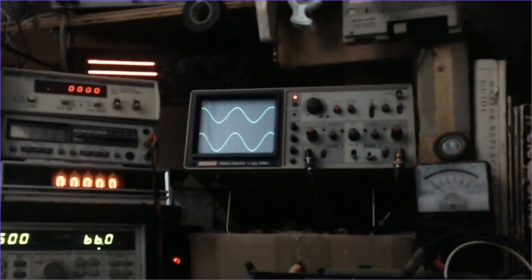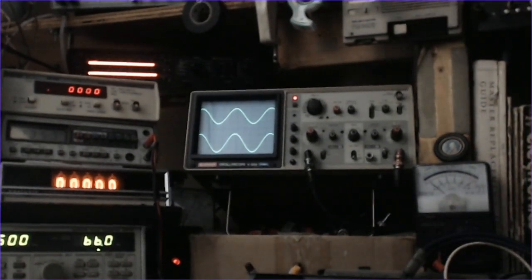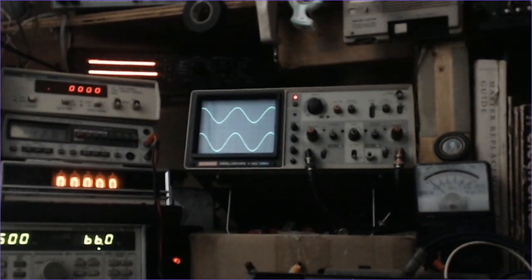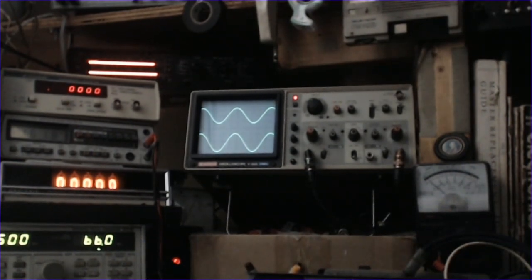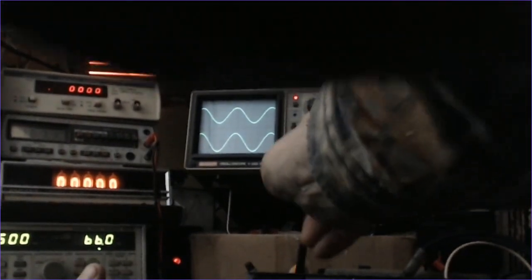When this item came in, the relays were intermittent. The boards had numerous heat stress connections, numerous to the point where all I had to do was apply just gentle torque, and just by putting the item on its side or just slightly picking it up one corner or the other would greatly affect one channel being there or not. And the item is now rock solid.